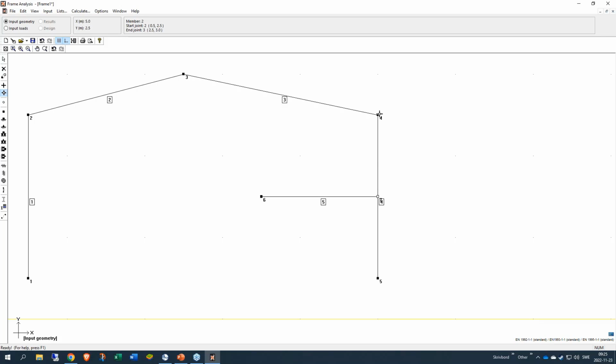So here I have a buckling length from 4 to 5, and number 7 is not interfering with that buckling. But if I would have used another, just the normal member, we can see it is divided. And this means that number 4 and number 9 will be braced out of the plane. And for element 4, it is now from element 9 to 5.